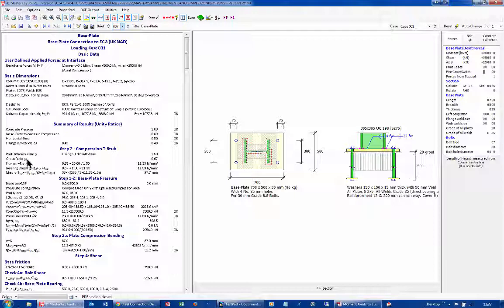And what's happening is that, well, if we have quite a deep pad so that we're coming down through it before the concrete is no longer there, then we can increase our bearing strength because the crushed material can't go anywhere and can't even start to crush. So the EuroCode in concrete gives us this lovely interaction formula for working out a pad diffusion ratio.